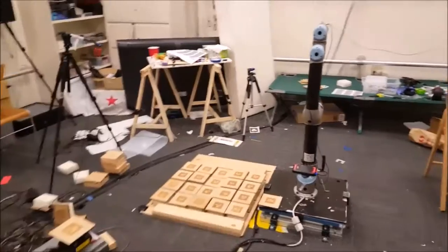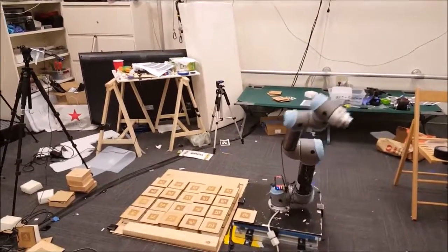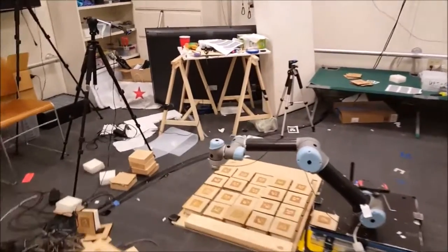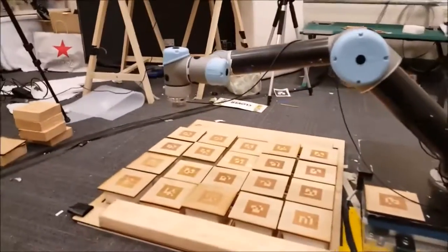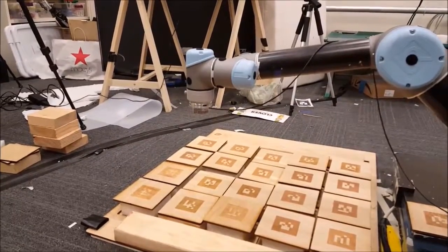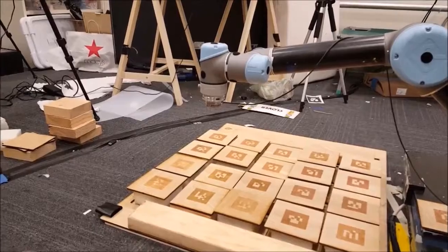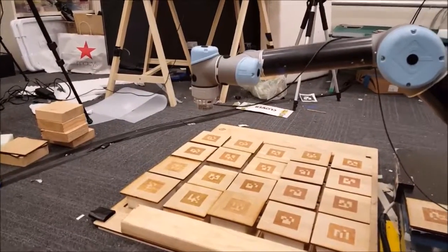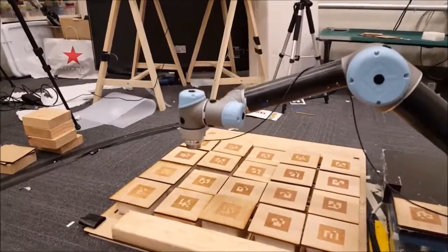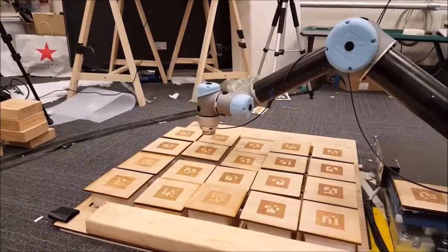and testing it. So now we're going to move the UR5 into a more favorable position to get it ready to start testing. So as you can see, the favorable position has put us in a way such that the end effector is oriented where the force sensor is ready to compress the blocks in Z and read forces. So now we're going to go down to a specified height above the block and begin traversing the grid.